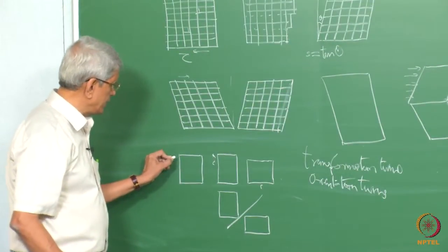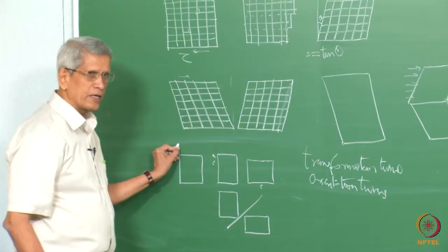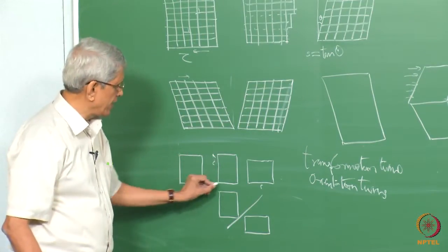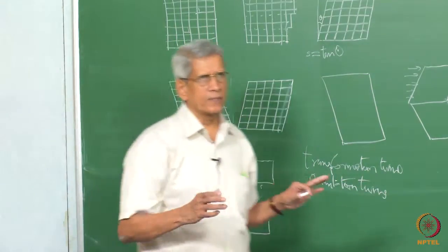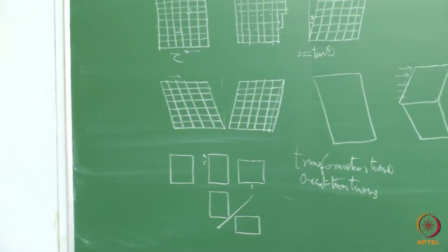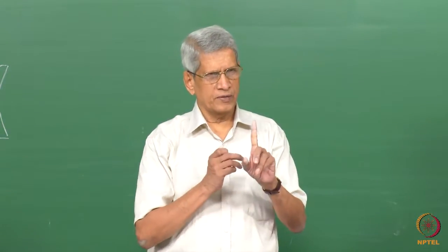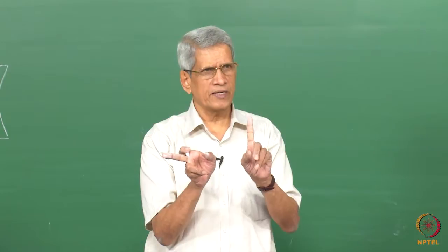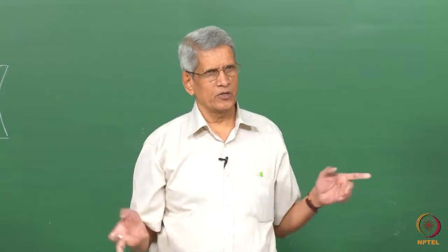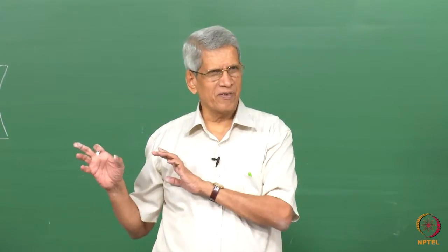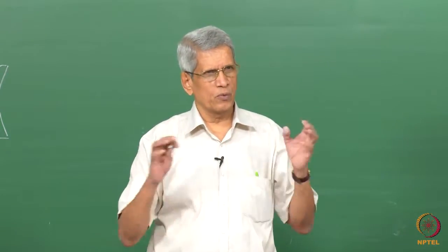Let us just concentrate on this FCC lattice itself. Suppose here the c axis has formed here, and another one forms with a c axis along this direction. But since the symmetry is being maintained, a, b, c we can't distinguish them, correct? Because of which, whether the c axis is in this direction or in this direction, as far as the structure remains cubic, it remains identical. We cannot distinguish them. That is what happens in the case of a normal transformation when FCC itself is there, when different nuclei form.